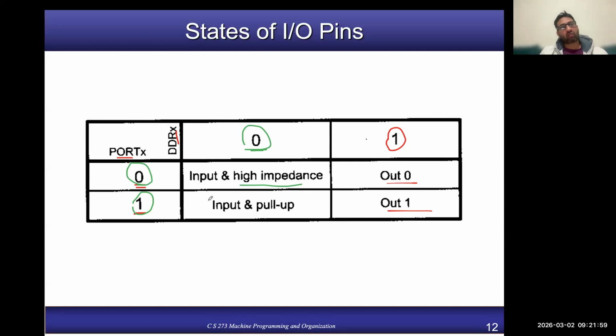When you connect it externally with an input, you will read that value. But when the external input is not connected to anything, you will be reading random values in the pin register due to noise, like 0 or 1. You cannot reliably trust those values.